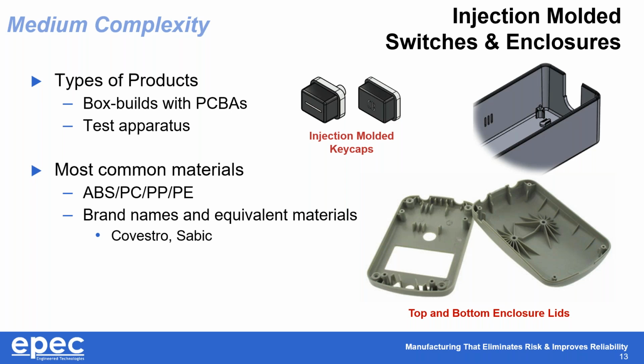So if you're trying to recreate a certain solution, it's not always clear if we need to match that 100% or can we develop a new enclosure that will fit whatever widget we're trying to contain and protect. Some of the most common materials we work with include ABS, polycarbonate, polypropylene, and other thermoplastics. We typically use brand name injection molded materials.